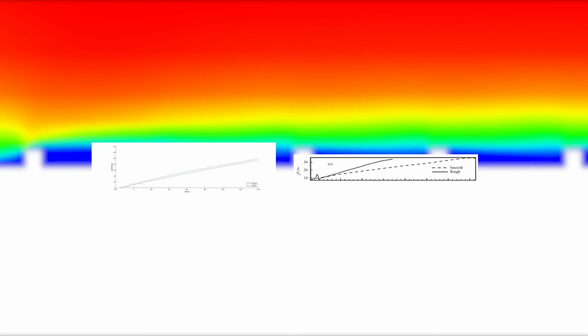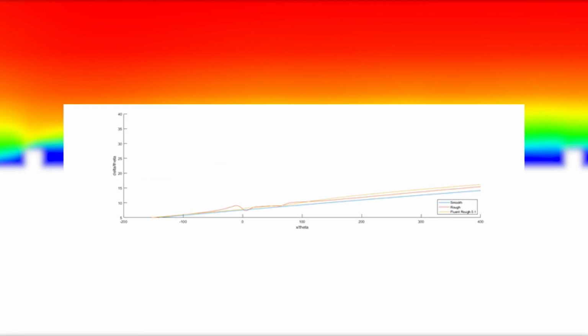With this in mind, the geometry for the rough wall consisted of 6 square rods. Each rod was placed 7 rod widths down from the next. No settings had to be changed for this section of the model creation, with the simulated rough wall matching the validation data. A brief study was completed to assess if Fluent's built-in roughness tool could be used in the place of the rods. This study showed that Fluent's tool could not accurately represent the rod-roughened wall and so could not be used. With this step completed, the actual testing with a rough wall and LEBU device could begin.